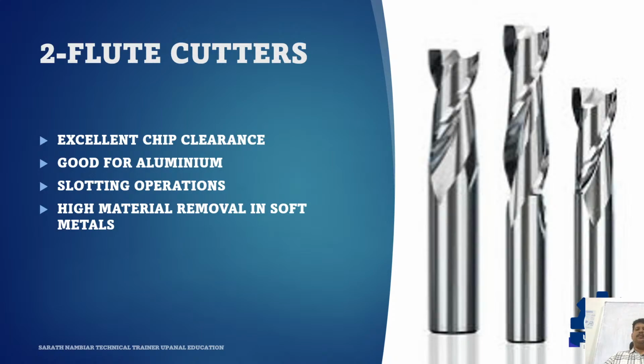The two flute is simple, it's effective, and often the first choice. Maximum chip clearance, deep slotting, softer sticky aluminum grades, lower power machines, safer beginner choice. These are the main features of the two flute cutters.